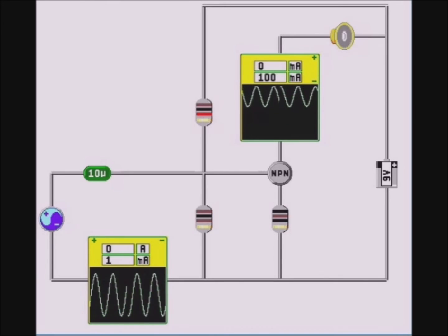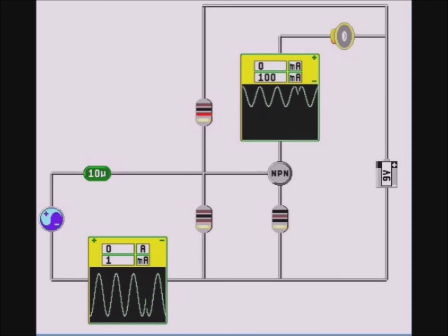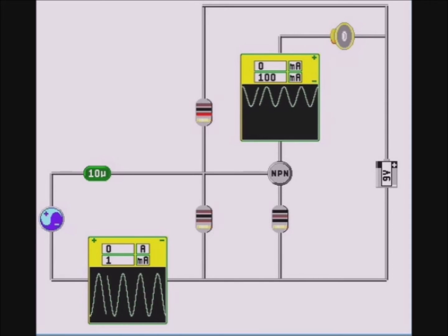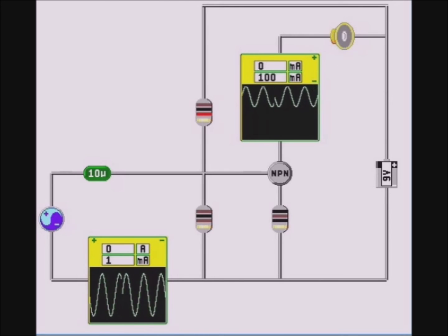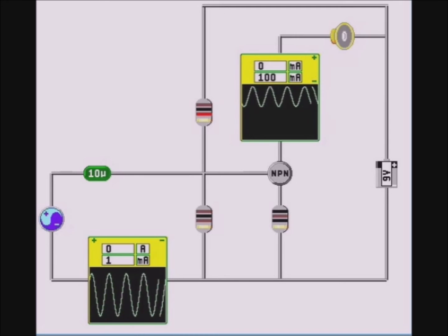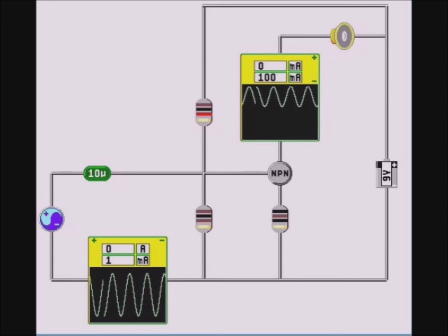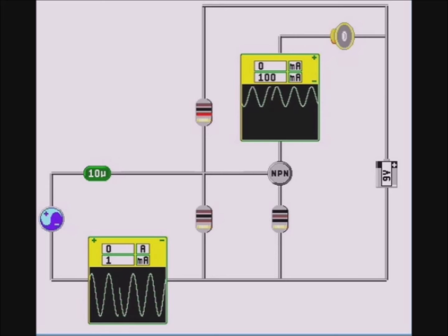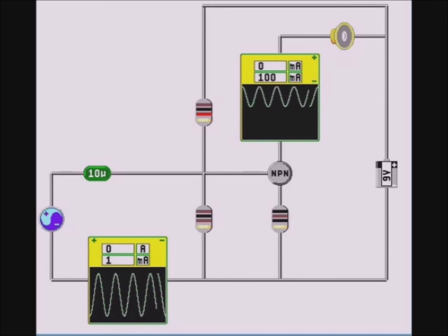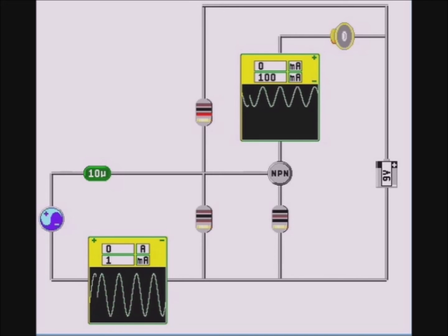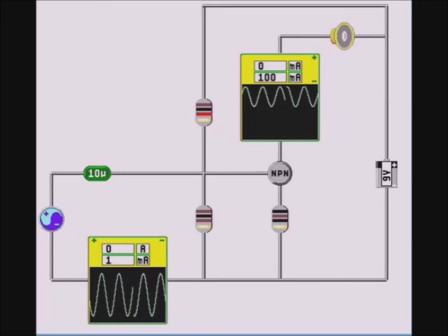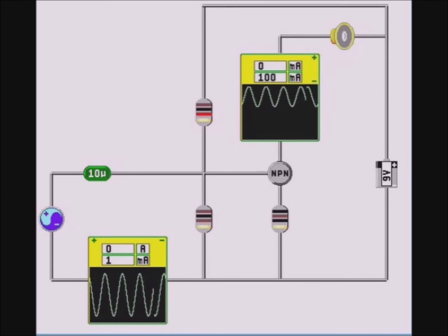The capacitor is continually charging and discharging in time with the wave generator, and this causes fluctuations in the current at the transistor base. These fluctuations are amplified at the collector by a factor of 99. Passing the current through the speaker from the collector will cause the speaker to sound. We are running the simulator at 1/100th of normal speed in order to see the waveforms. This is the sound generated, which is similar to that produced before.